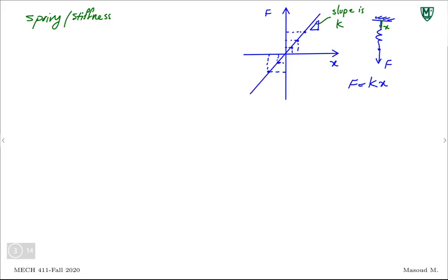Now, we also talked about objects, solid materials. We are not just dealing with springs. Let's say I have a bar. You said we can replace this bar with a spring. Now, in this case, how do we find the stiffness of that spring? Remember, we said, for instance, if it's longitudinal direction, I'm pulling it, K equivalent would be AE over L, A being the area of that bar or rod I'm pulling, L being the length.